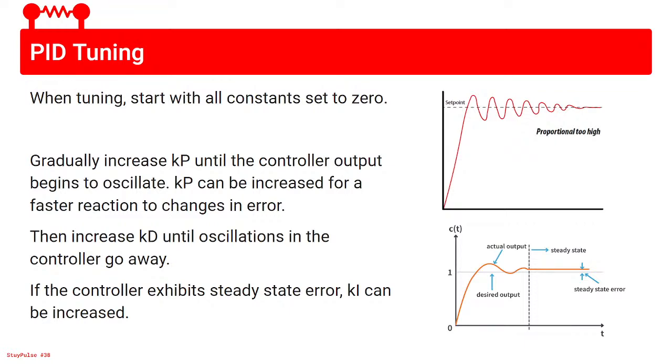This is that point about if your drivetrain, for example, is coming in hot on its target, Kd will slow it down because Kd accounts for how fast it's moving. That's why you can make the Kp oscillate and then fix it with the D term. And then if the controller exhibits built up error, you can use Ki to fix that.